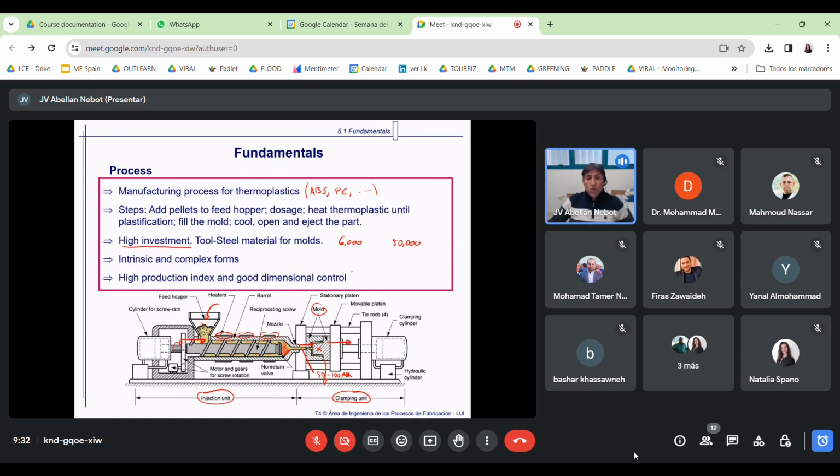But imagine that you want to produce a few parts. Obviously, injection molding is then a very expensive process. That's where we find rapid tooling, where we can produce tools, that is molds, at a very low cost, so you can produce parts, but in low quantity, because the life of these molds is very short. But this is another topic, about rapid tooling.